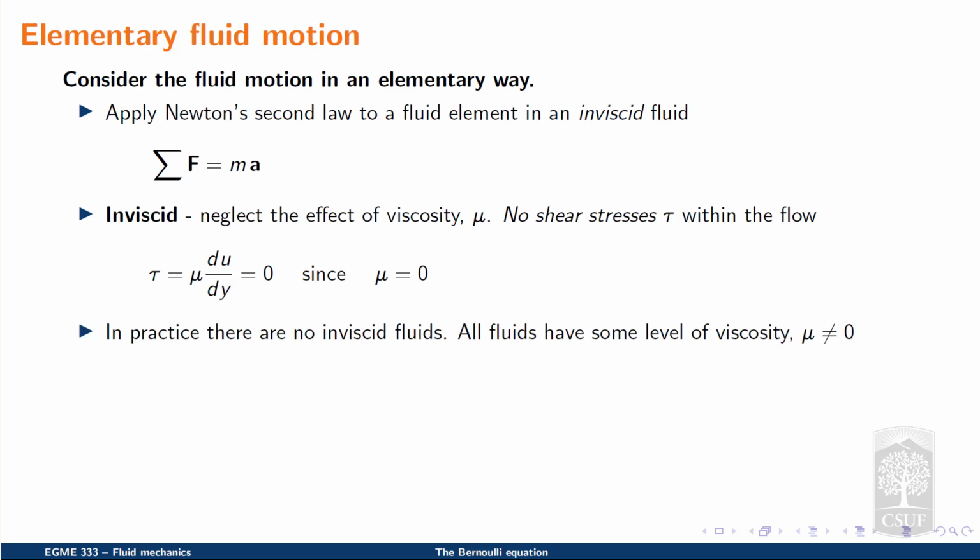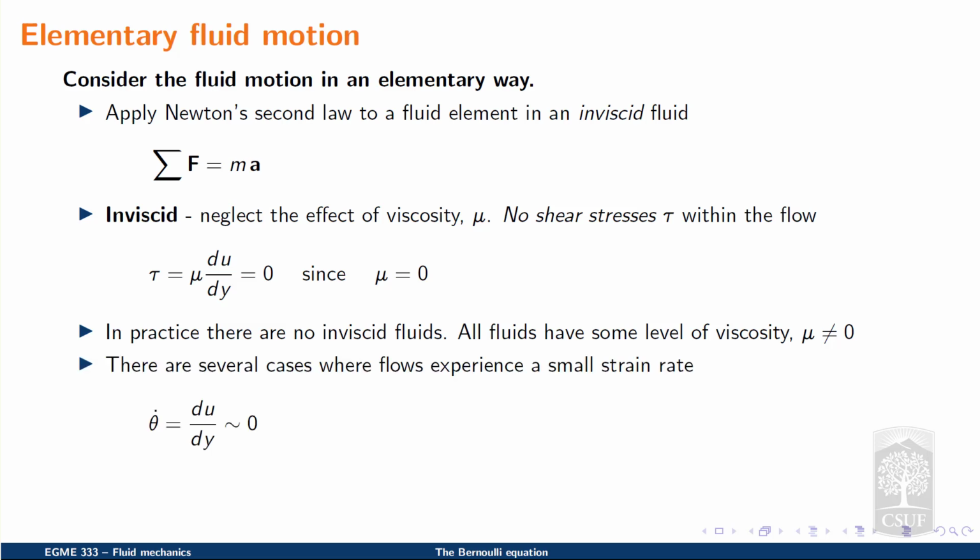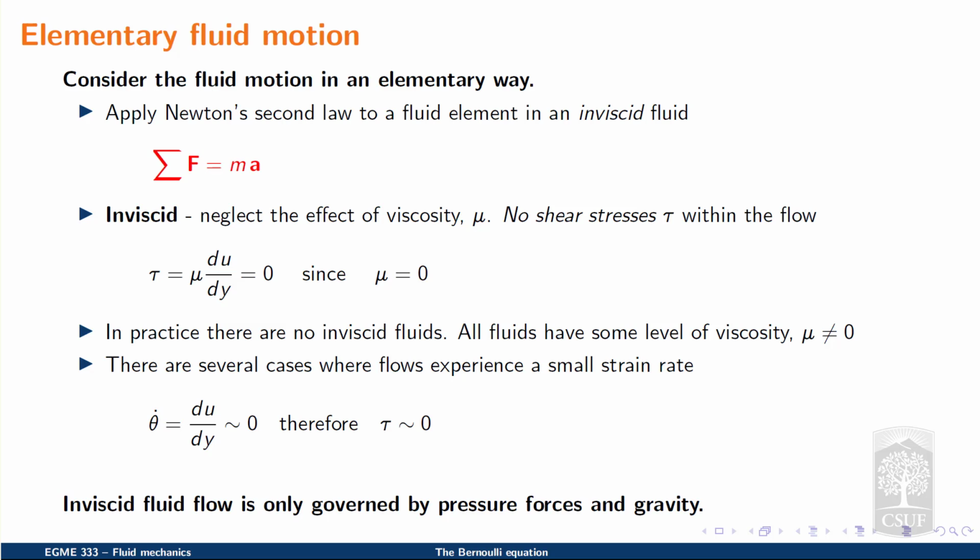Note that in practice, there are no inviscid fluids. All fluids have some level of viscosity. However, there are several cases in practice where flows experience small levels of strain rate, where du dy is approximately or close to 0. Therefore, the flow is experiencing a small or a negligible amount of shear stress. So when we are dealing with inviscid flows, those flows are only governed by pressure forces and gravity.